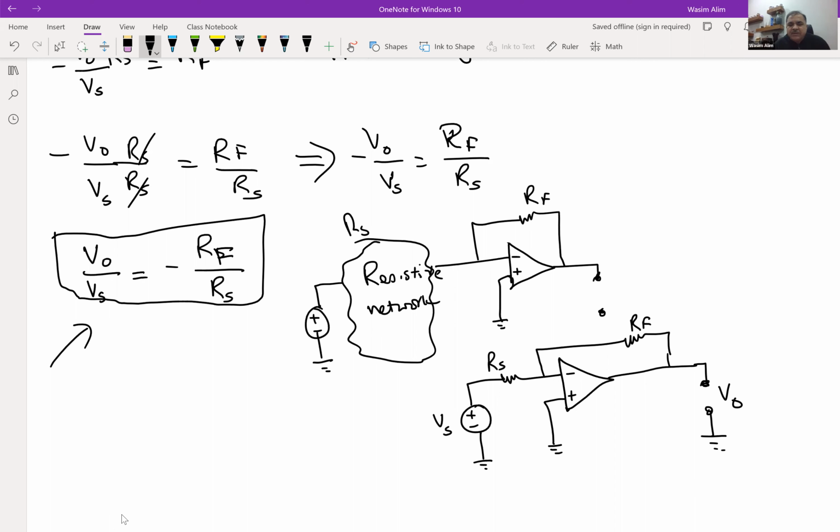So you have this R sub F, which is the feedback resistor, and that is going to define what the gain is. Based on this formula, if you see the feedback resistor connected to the negative terminal of the op amp, then you can use this formula and find the gain of it. Okay, so let's look at an example here.